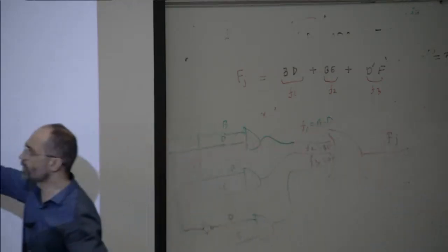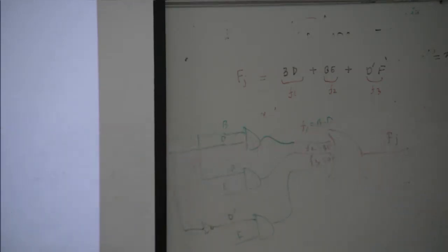Please look here and think. How many input OR gate do we require? 4 input OR gate. And then we need a 3 input AND gate, then a 3 input AND gate, then a 3 input AND gate, and then a 3 input AND gate. We also need 4 inverters. Why? 1 inverter for A bar, 1 for B bar, 1 for C bar, and 1 for E. Got it? So now you can do these tasks. These are the tasks.